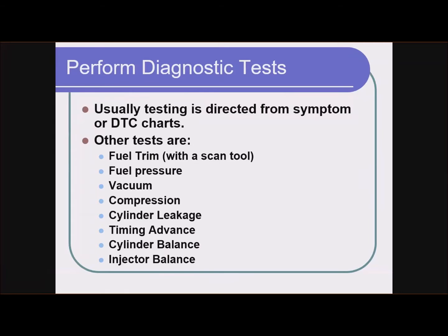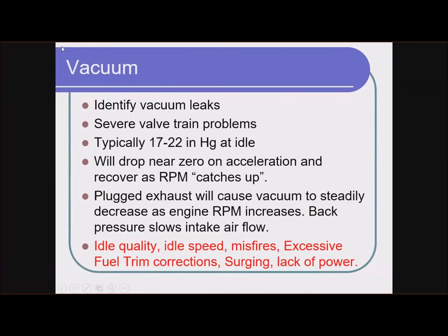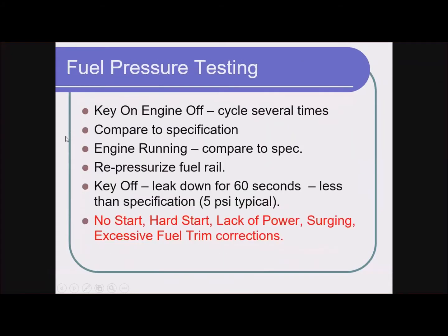All right, so if we move on to fuel pressure testing, right? So there's two things that we're going to test here. We're going to test the actual pressure that the fuel pump and fuel pressure regulator combined are supplying to the fuel rail. And the second thing we're going to test is when we shut the key off, when we park the car, is the fuel rail maintaining some pressure for the next startup?